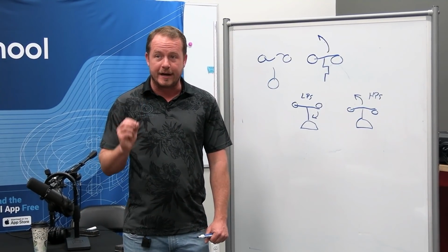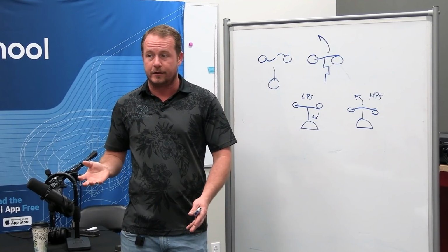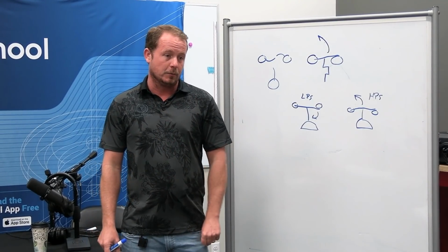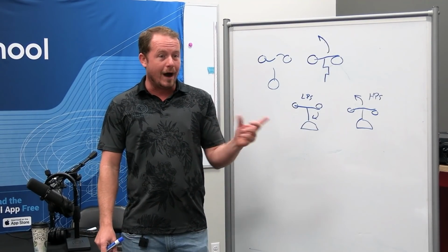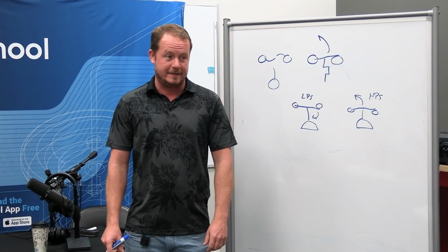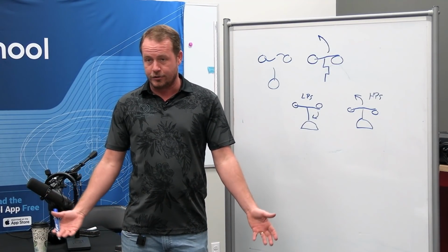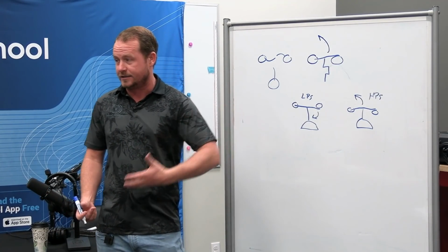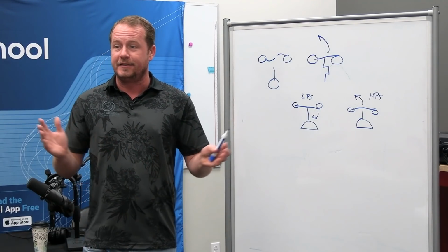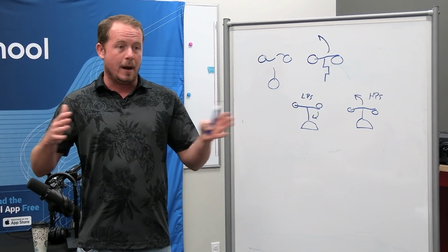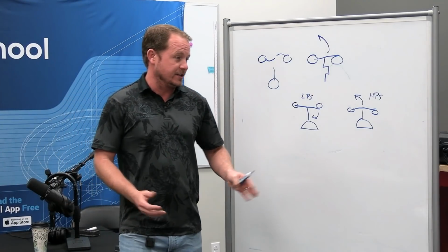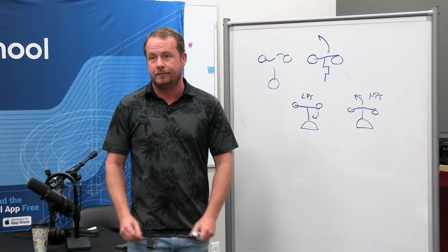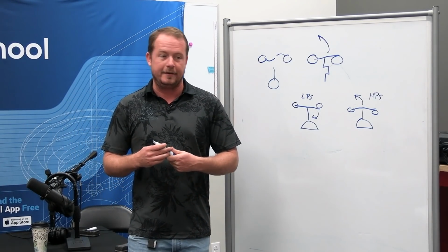First thing you check would be your connectors, check your wires, make sure they're not broken. But then at that point, you would jump out the low pressure switch and figure out why it went out on low pressure in the first place, because it's probably low on charge or has a restriction or something that caused it to go off. Safeties don't fail in the opposite position for no reason, just like a door doesn't fail if somebody didn't open it or close it or slam it.